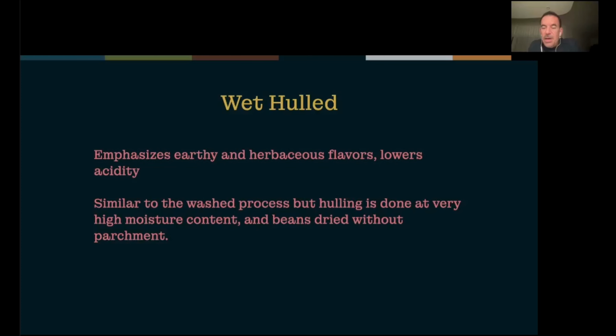But if you find an optical sorter where you can program it by showing it a sample of the coffee and saying this is good, and showing another sample and saying this is too light, showing another saying this is too dark, then that is so much easier to use than one where you have to master entering blue, red, green color spectrums for each coffee. It's just so much easier to show the machine a sample and train it by sight. So they can be quite easy to use, and they can be quite difficult to use depending on the sorter.